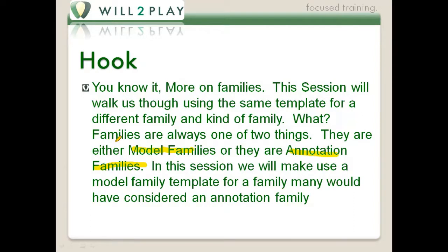Model is true size, right? It's a desk, it's a table, it's a 3x5 desk. Doesn't matter what scale the view is, that desk is physically 3x5. And annotation, right? Annotation, we're talking about text on top of the model. Right, and that's not going to scale according to the view. Annotation families scale independent. They don't care.